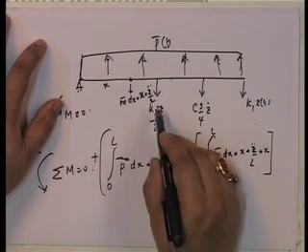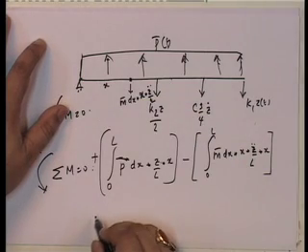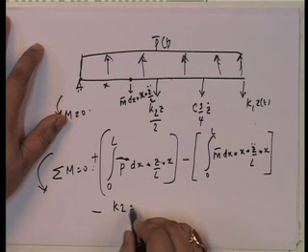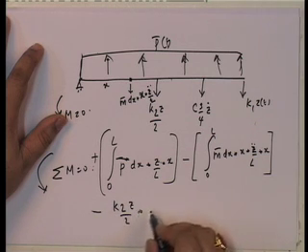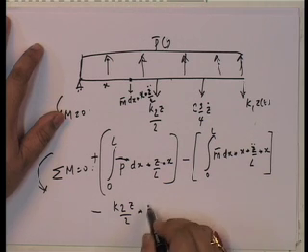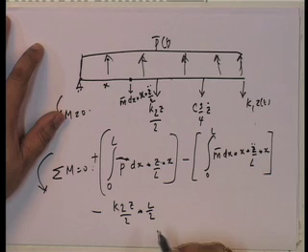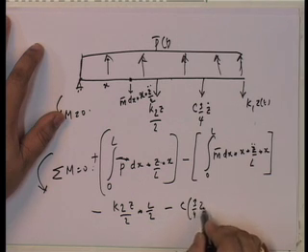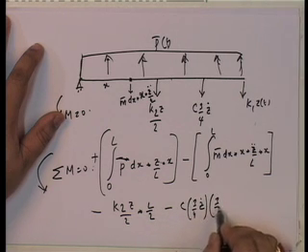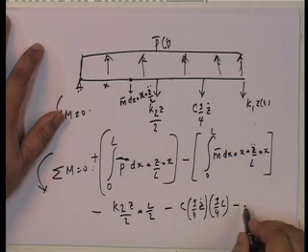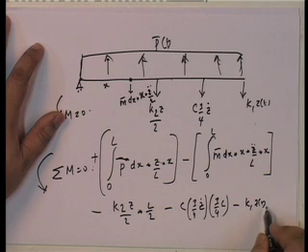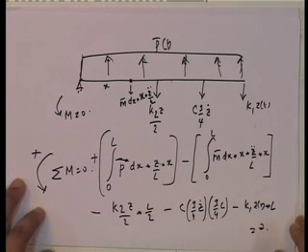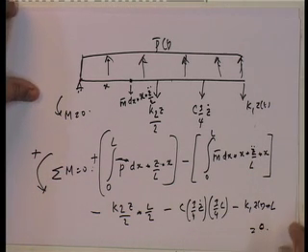Then what do I have? Then I have k 2. So, this is also anticlockwise. So, this is going to be negative. So, negative is going to be equal to k 2 z by 2 into what? Into L by 2, right, minus 3/4 z dot into 3/4 L minus k 1 z of t into L. That is equal to 0, and that is my equilibrium equation.